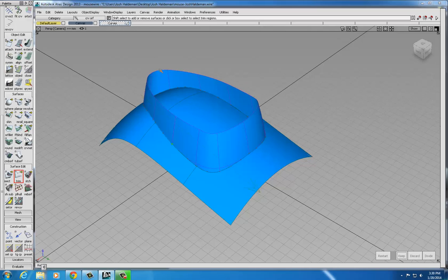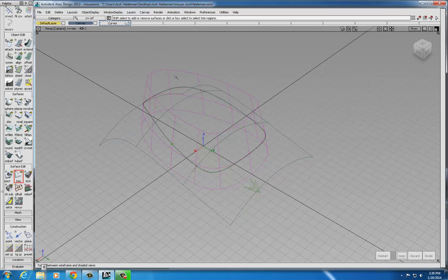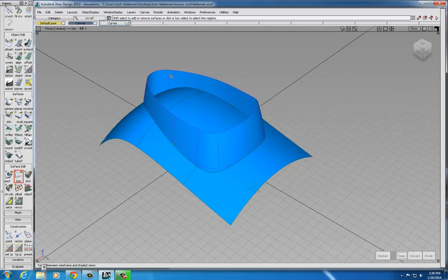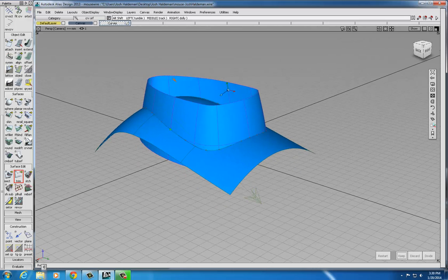So pick it somewhere where there's no other isoparms or contour lines behind that selection. If you're not sure, turn off the hardware shade. You'll be able to see that there was nothing else behind there. In here, it might be confusing. The program might not know which surface to pick. So it's a good idea to pick out in this general area or move your view to an area where you know there will be nothing behind it.